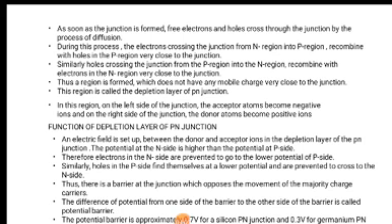On the left side of the junction there will be the acceptor atoms, and on the right side the donor atoms, which we call positive ions. And what is the function of the depletion layer PN junction? First, an electric field is set up between the donor and the acceptor ions in the depletion layer. So the potential at the N side is higher than the potential at the P side. The electrons on the N side are prevented from going to the lower potential side. Similarly, holes coming to the N side face a barrier, and this difference is called the potential barrier. The barrier is approximately 0.7 V for silicon and 0.3 V for germanium.